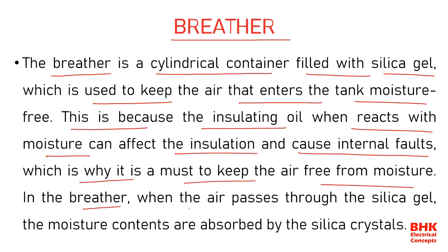In the breather, when the air passes through the silica gel, the moisture contents are absorbed by the silica crystals. So that is the reason why we are using the breather in the transformer.